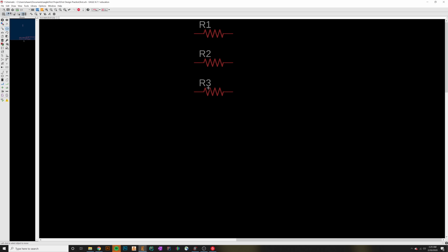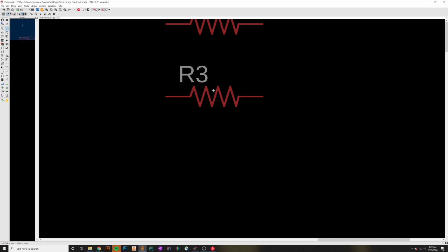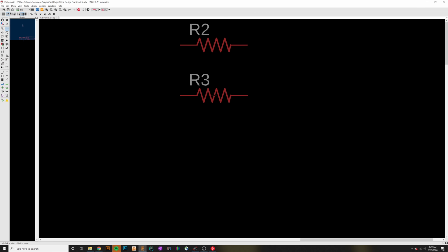The only way I can interact with components is by first clicking on their crosshairs. Every single component will have a crosshair associated with it, and if you're not clicking on it, you will not be able to move or interact with the object. And that goes for every single tool here. Okay, so keep that in mind.